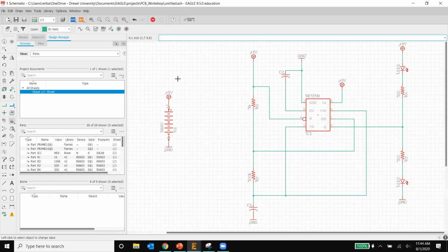Yeah, about those 9-volt sources and the grounds that you put around the schematic, are those just links to the power source we put in? Yes, basically yes. But if you do it this way, you're telling EAGLE, because a computer is basically dumb, like you're talking to it. So by doing this, you're telling it that there exists a signal of 9 volts. And there exists a signal ground.